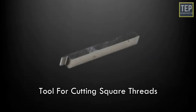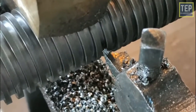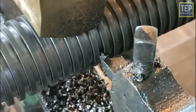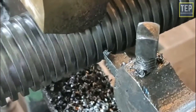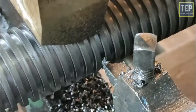Tool for cutting square threads. The side clearance of the tool for cutting square thread is of prime importance in order to prevent the tool from interfering or rubbing against the vertical flank of the thread. The width of the cutting edge should be equal to half the pitch of the thread. Small clearance angles of 1 degree to 2 degrees are provided at the side of the tool to prevent the surface from rubbing with the work.